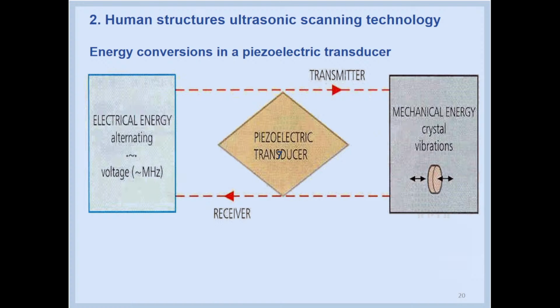The electroacoustic transducers used in the ultrasound range operate on the basis of various phenomena. In particular, the piezoelectric mode is one of ultrasound generation. This mode is illustrated by this diagram. If pressure is applied to the surface of appropriately cut plates or discs of certain monocrystals, for example quartz, electric charges are generated.